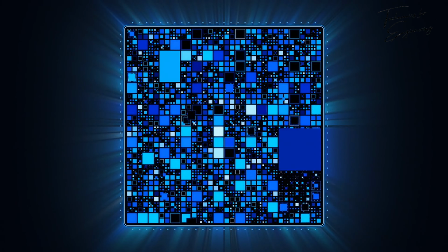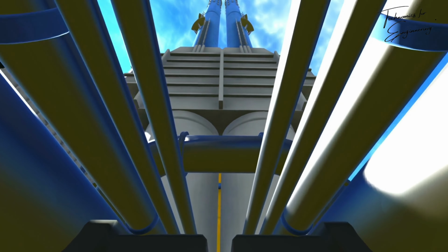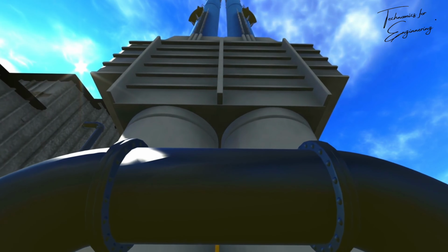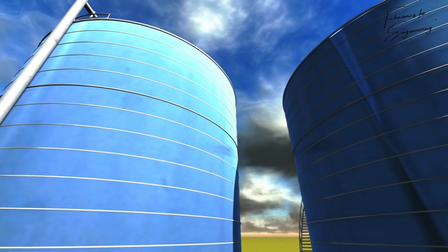The fetched instruction is decoded in this stage. The instruction decoder analyzes the opcode, operation code, to determine what operation needs to be performed. During this process, the necessary operands, data, are identified, and if needed, data is fetched from registers or memory.